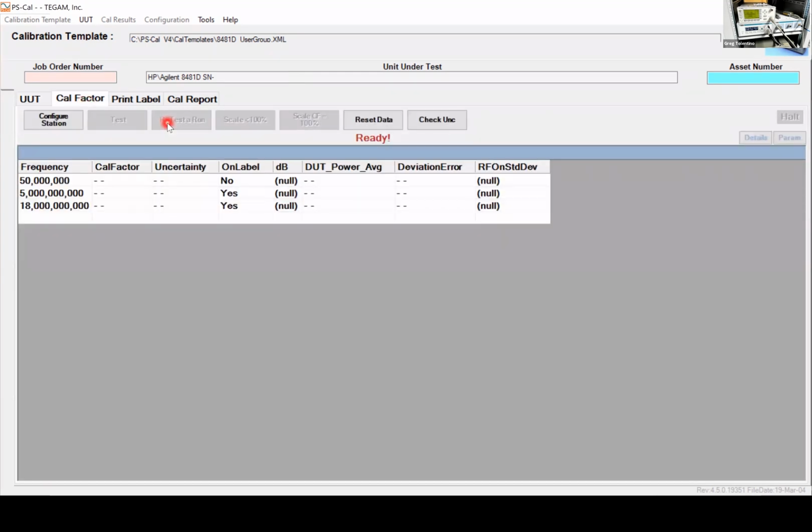So I've created this template prior to getting started on the webinar. We're going to go ahead and just go straight into Cal Factor. I deleted out most of the frequencies for purposes of this demo. I just want to show the process and how to get this calibration started. So you can see in the video, I have an E4418 Bravo and a TEGAM 1830A along with a TEGAM 2505A. That's all the test equipment we'll need. The generator is sitting down below. So that's the equipment that we'll be using for this test.